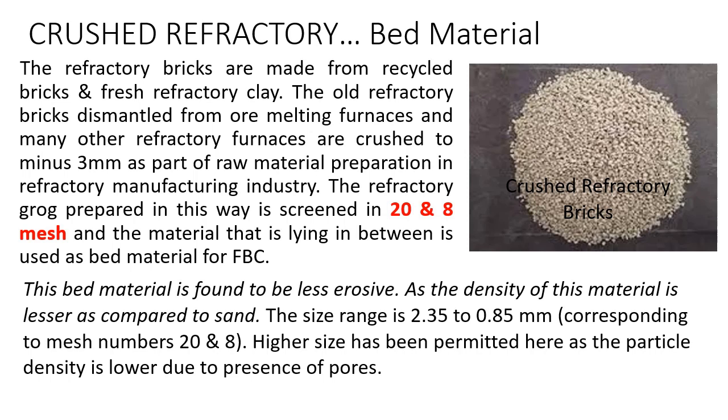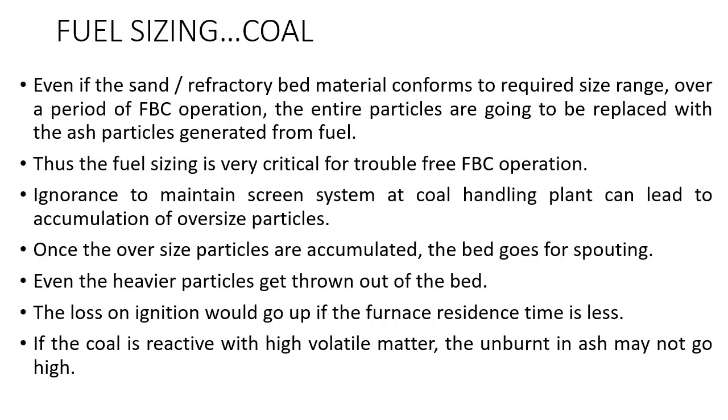Fuel sizing. Coal. Even if sand or refractory bed material conforms to the required size range, over a period of fluidized bed combustion operation, the entire particles are going to be replaced with the ash particles generated from fuel. Thus, the fuel sizing is very critical for the trouble-free AFBC operation. Ignorance to maintain the screen system at the coal handling plant can lead to accumulation of oversized particles. Once the oversized particles are accumulated, the bed goes for spouting.